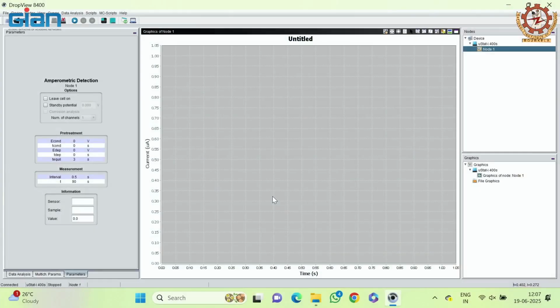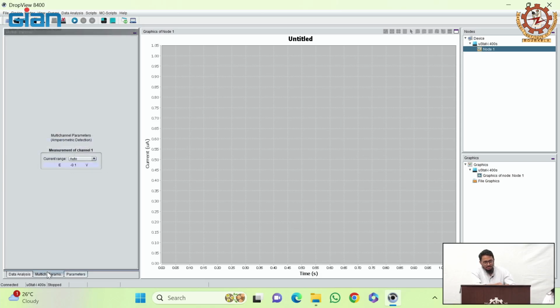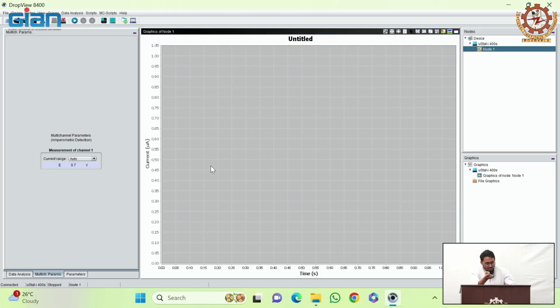So, in point of care diagnostics, generally we combine microfluidics with these sensors, so that the microfluidics ensures that the fluid is properly covering the sensor. So here we are doing it manually, ensuring that it is covered properly, but if you have, let's say, a glucometer, if you look at the strip, you put a drop of blood, and that blood is drawn through the microfluidic channel, and it covers the sensor properly. So that process is automated using microfluidics.